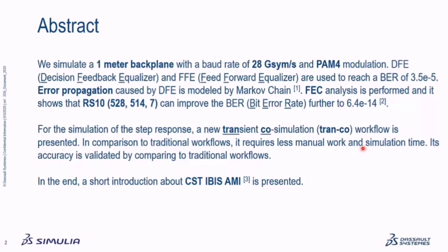This technique is almost mandatory for this high-speed interconnect, because the channel is so long and the data rate is so high. We have to use FEC to reach a bit error rate in the range of E-14.